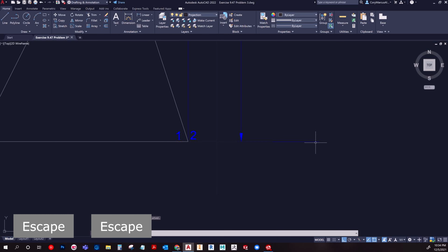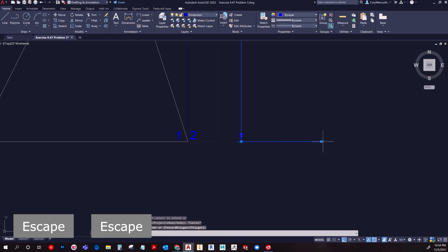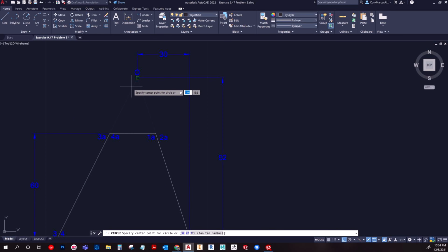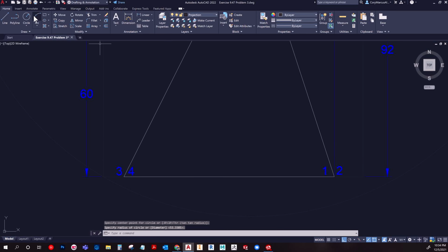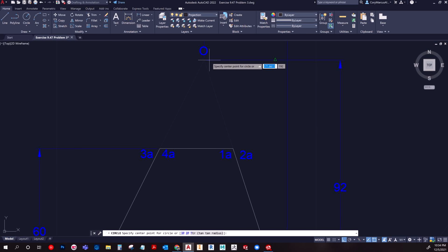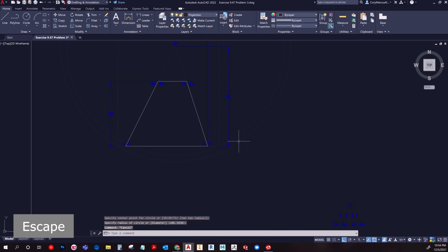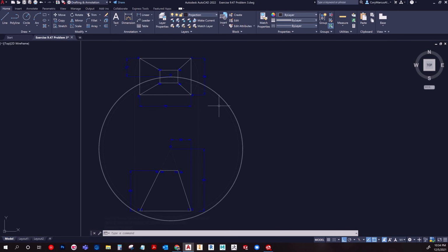We'll just move this little lad. Okay, so now we know the size of our two largest circles. So from that origin point, just like you did in top view, we are going to draw to that crossing. Alright, so we'll do the same on this side. And essentially what we have here is those primes that we talked about over there, except this will be the actual true length of the slanted lines themselves.